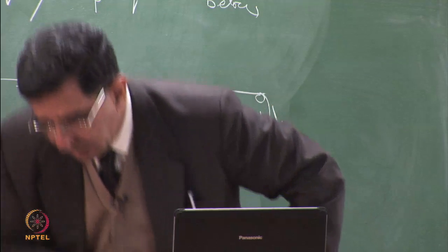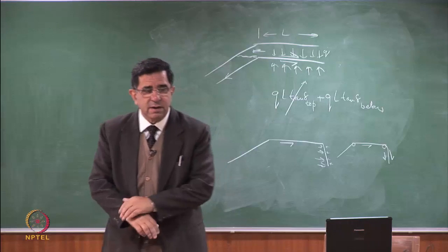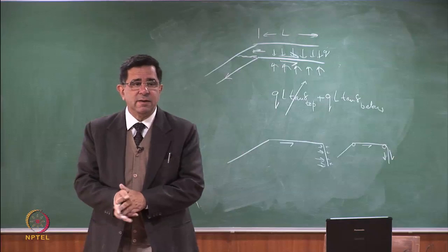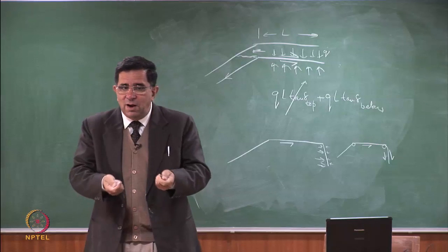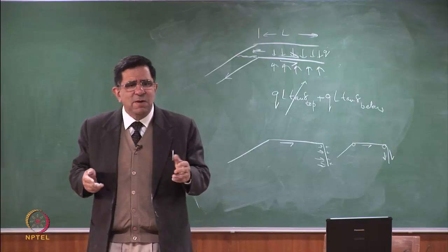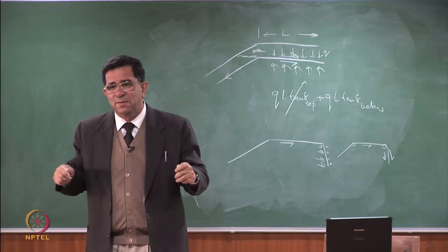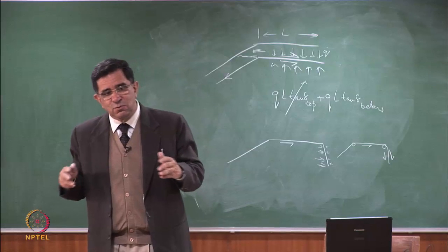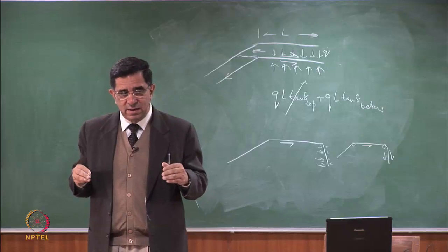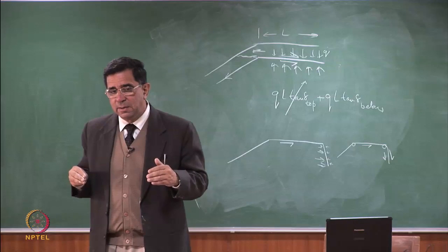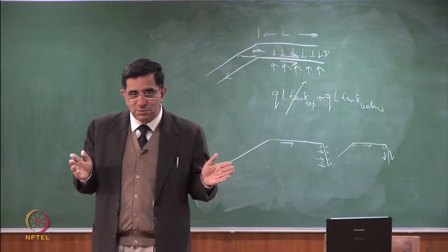So with this, we end our discussion on slope stability, and in a sense, philosophically, if you are not relying on T, then it's a passive system, right? There is no tension in the elements. So if you use 4.5:1 or 4:1, you may not have an issue of requirement of anchorage, but you want to go to 2.5:1 with the 40 kilonewton per meter I showed you.